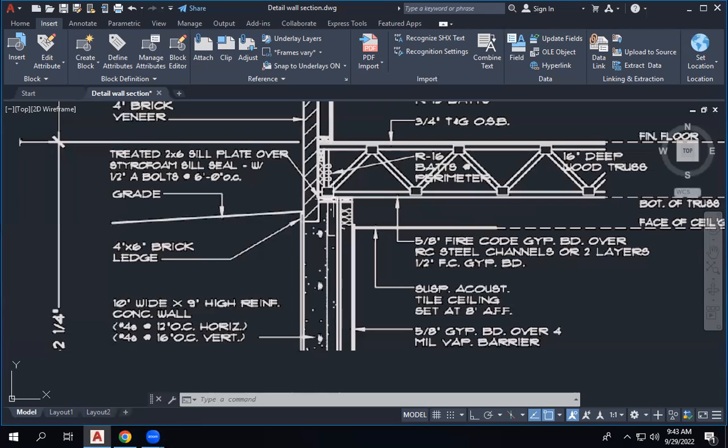So you can now draw this one here, the truss supporting on the concrete wall with the steel plate supporting with anchor bolts into it. And this one is just the simply supported one. It has the timber stud just below the truss, and your insulation and this gypsum board can go right up to here, or it can stop here, because see here, it stopped here because there's a ceiling here. After the ceiling, no need to put the gypsum board right up to the top, but you can have it. That's no issue.